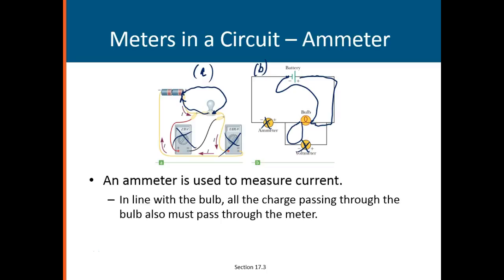No. What you have here is from the positive side of the battery down to the bulb, then from that same side of the bulb up to the negative side of the battery. And a loop over here on the other side of the bulb, and then back to the negative side. There's no way. All the current's going to go through here and not even touch the bulb at all, and this loop goes out of nothing. So that bulb won't light. So B will not light either.